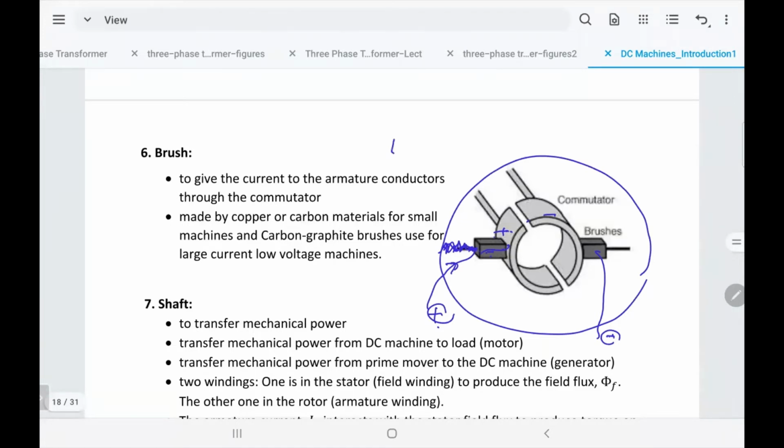Of course, it cannot be hanging in air. There's a cylinder of insulating material, and then they put the pieces of metal around it. So it's on a shaft made of insulated material, and the space between the 2 halves is insulation material. There is no conduction. So what happens when it's moving like that? There is a moment when the brushes are not touching the metal, or are between the 2 metals. So a high voltage change happens on the commutator, which causes sparks.